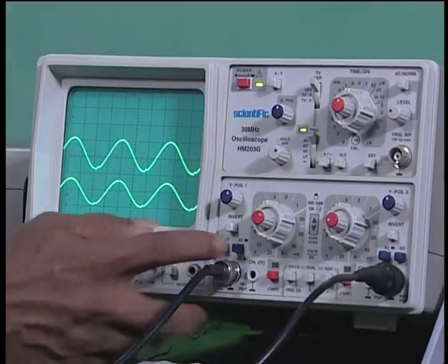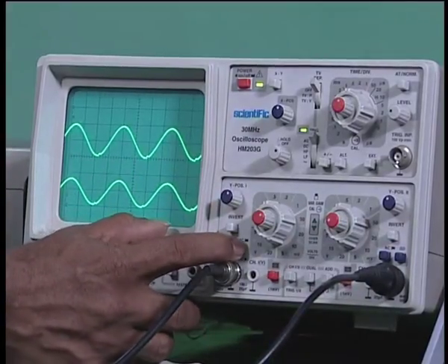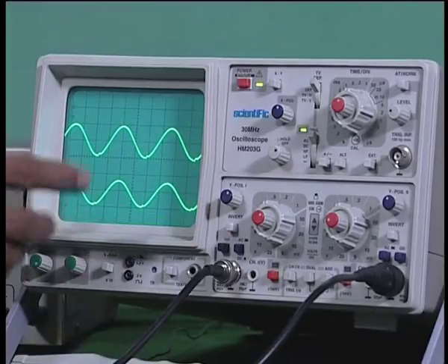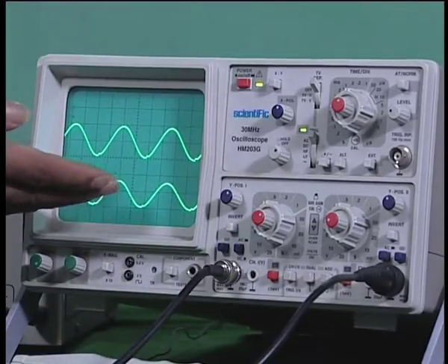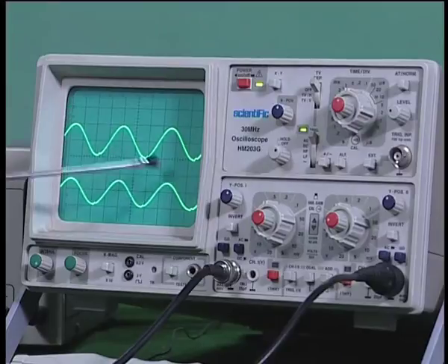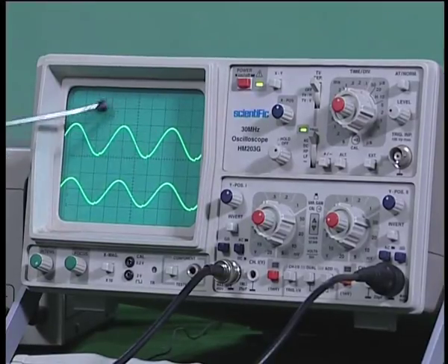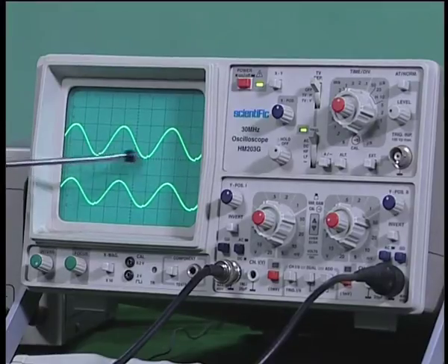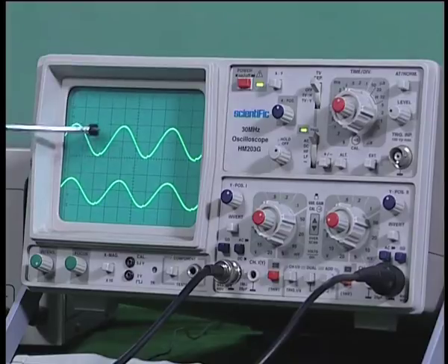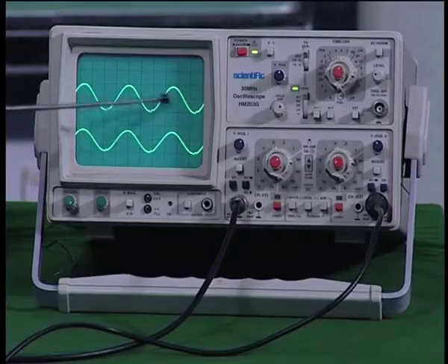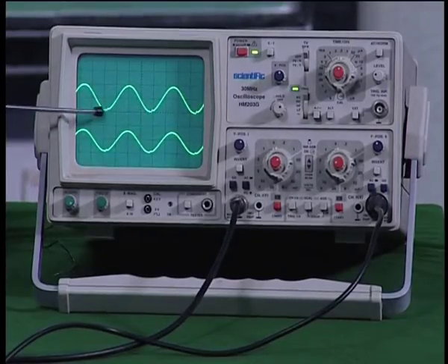Whereas, in the top one, you see all of them are AC, but with reference to a 0 line, which is at the bottom, and therefore, it is a varying DC, sinusoidally varying DC, all with reference to this reference point. Therefore, it is positively clamped, that is what we mean. So, this is the way to identify the DC clamping here.